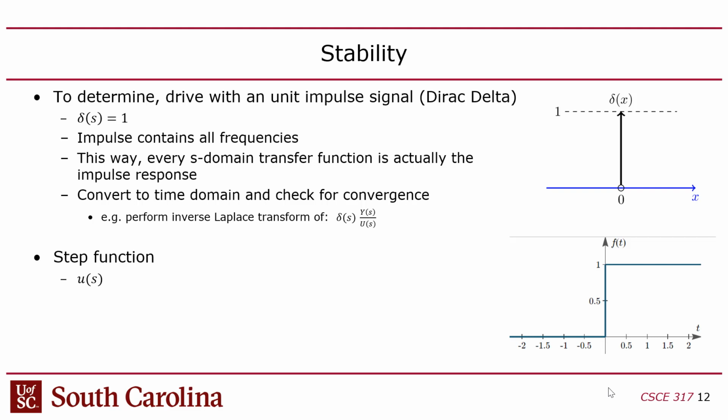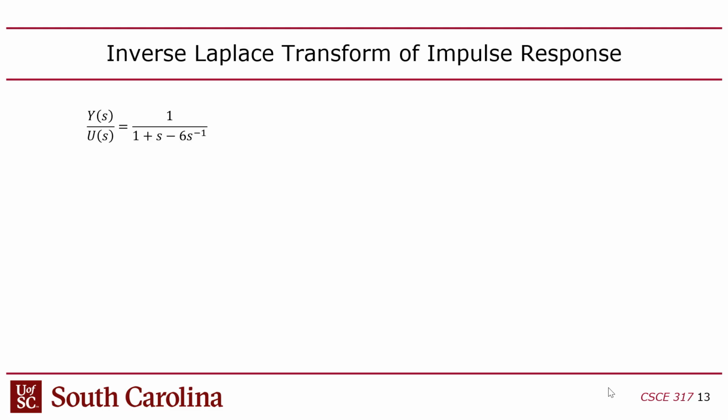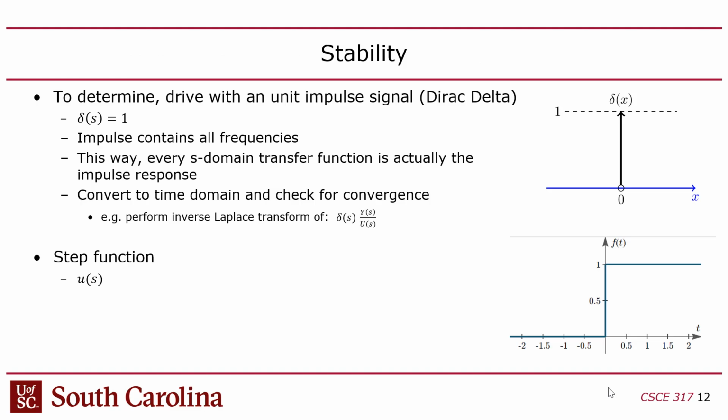Sometimes people want to know that, right? Normally, when you control something, you assume that the system as a whole is stable, even if the thing you're controlling by itself is not stable. You can determine stability by hitting it with an impulse or a step function. Why does that determine stability? What is special about the impulse or the step function?